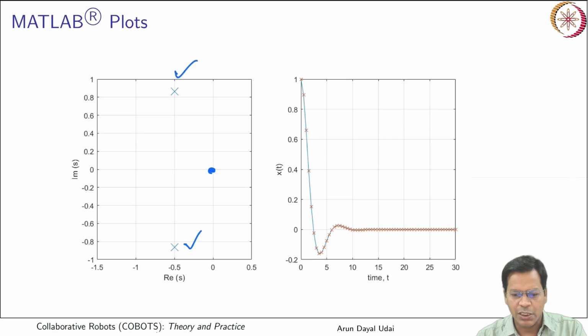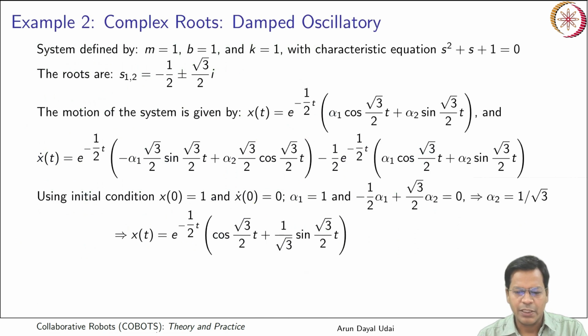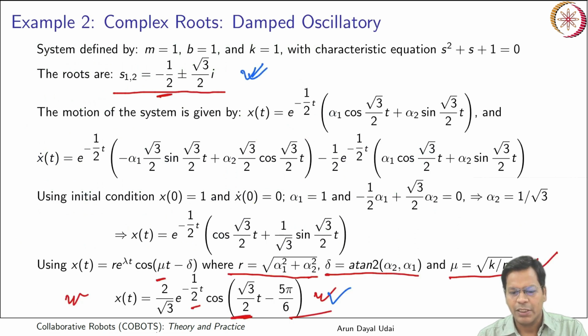And your system, you see, this time it started from here. It overshoots to some value, overshoots on the other side, and comes back. It is still oscillating, which is not clearly visible here, but it is oscillating and finally reaches 0. So what kind of system did you expect here? It is a damped oscillatory nature.